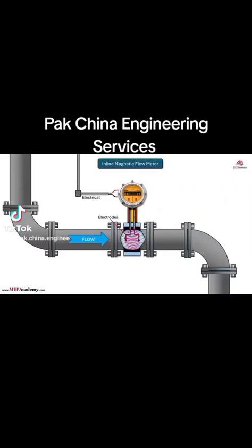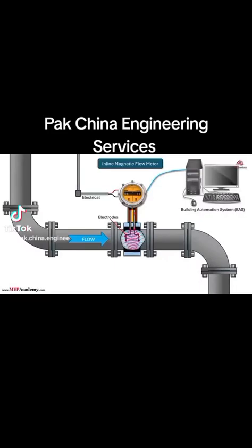The information gathered from the meter can be sent to a building automation system for various sequence of operation control strategies. There are no moving parts or obstructions in the flow path. This provides a very low to no pressure drop. This makes them a low maintenance meter while also being easy to calibrate. You will need at least 3 or more diameters of upstream straight pipe and 2 diameters for downstream. This is to ensure accurate readings. Check the manufacturer's literature as they can vary.